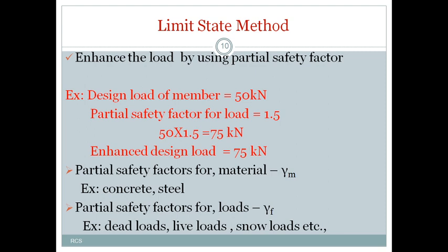If I design with the enhanced design load, then I will get more cross section than with the actual design loads. We know that more cross section leads to more stability of the structure; it has more resisting capacity to the externally applied loads. That's why we are enhancing the design load. But we cannot blindly enhance the load; there are rules and regulations, and there are provisions from the code. According to that code only, we have to enhance the design load.